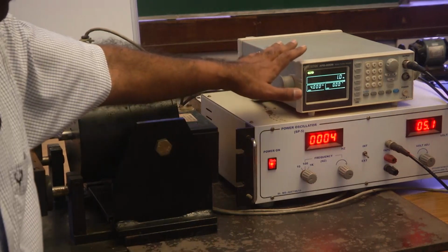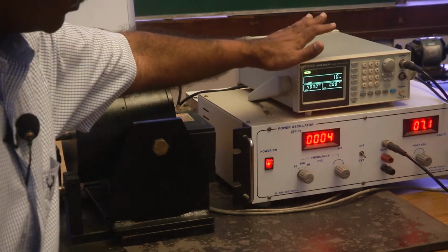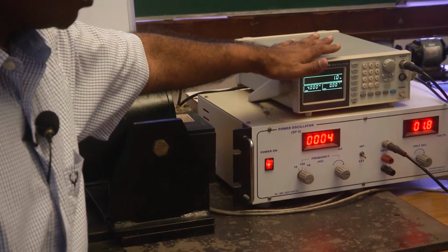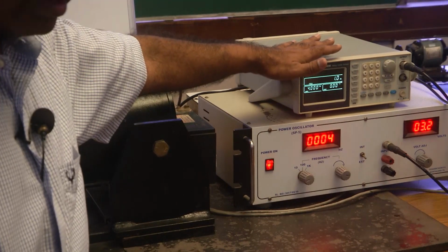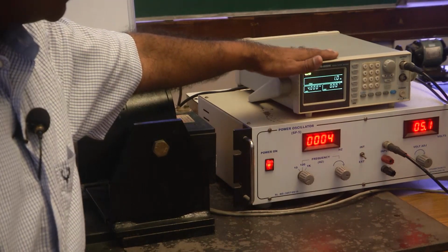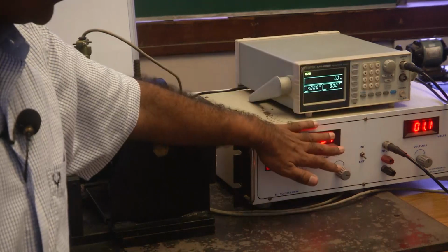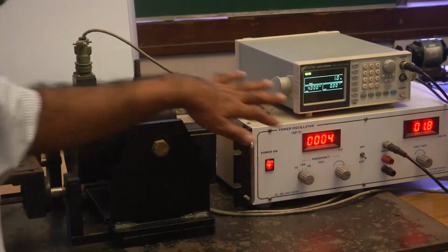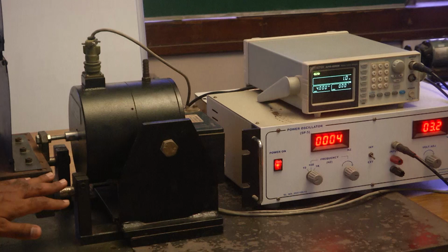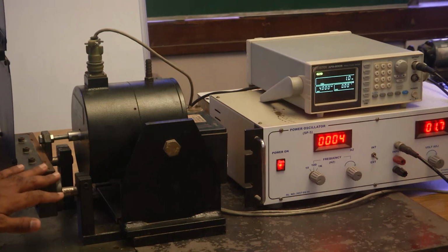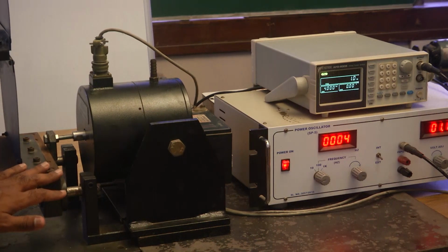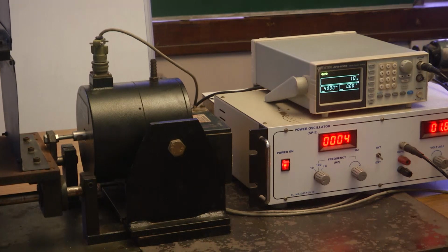And so that is how we have done here. We have initiated a harmonic signal of a given frequency using this signal generator, fed it through the power amplifier to the oscillator, so that the base motion to the base plate here can be adjusted based on our requirement.